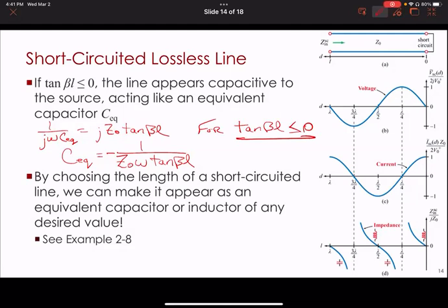So there's something called the self-resonant frequency. And when you go high enough in frequency, like the kind of stuff that we're dealing with here, there's a transition frequency where a capacitor might look like an inductor. Or a capacitor may still look like a capacitor, but it has a totally different value of capacitance.